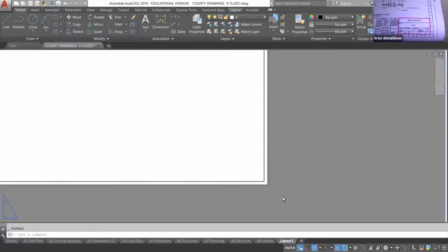In paper space, I can just draw normally. And it's going to understand that I am in paper space and there'll be no scaling. It's just like drawing straight on the piece of paper. Okay. So I'm actually going to use a relative coordinate, shift @, and I'm going to go -4, 2.